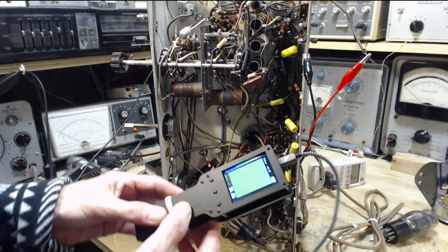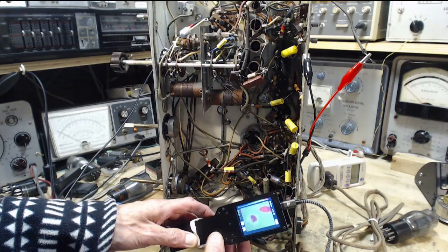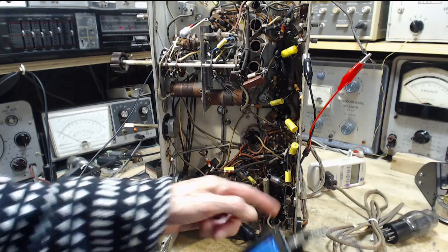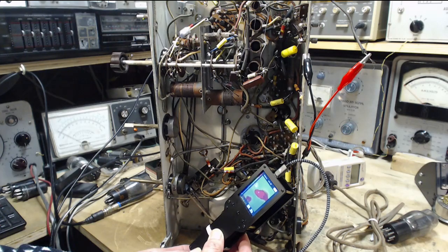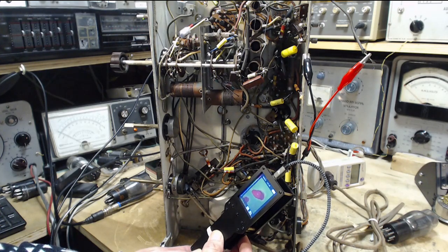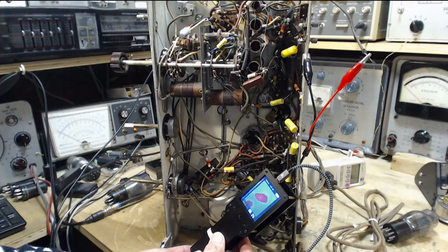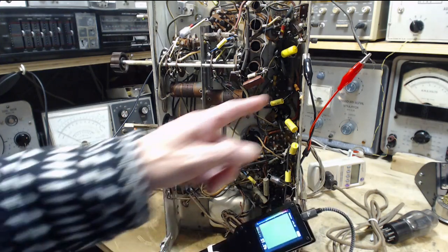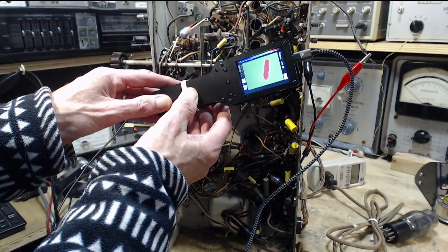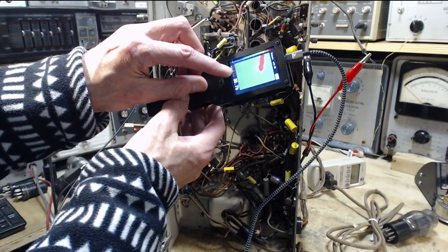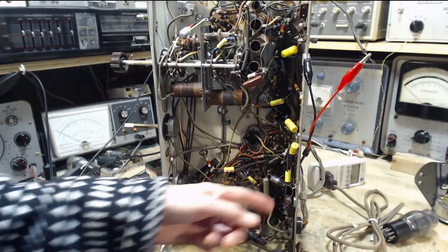Okay, let's go through the radio now. You have an idea what I'm up to. So we see two distinct red things here. This one is much redder, and this is this resistor. So that's telling me that resistor is running at 70 degrees, even hotter. 70 is pretty warm. Yeah, we'll look at this resistor up here. Ooh, and it's running at, I'm reading the small red print here, 60 degrees. So it's not as hot. This guy's the hot guy. I mean, that's why the paint is coming off.